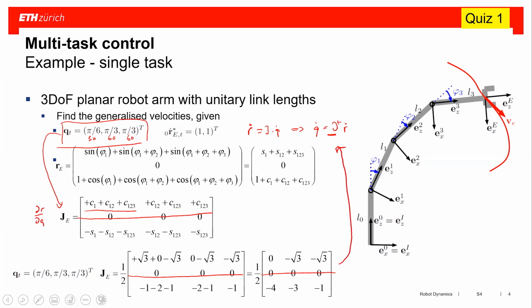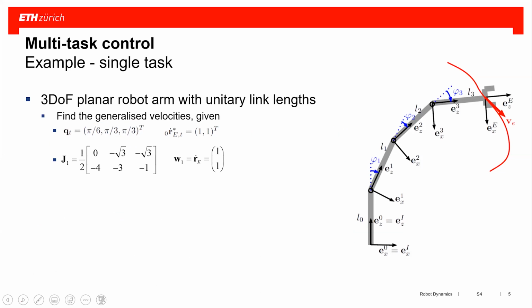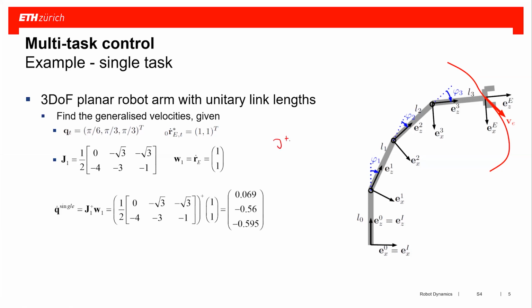All right, now we have the Jacobian, and all we need to do is take this and evaluate this formula up there. So we have to take the pseudo inversion of that. This is straightforward. So the pseudo inversion J plus is equal to J transposed times (J J transposed) to the power of -1. So what we're doing here is creating, with this J transposed, a square matrix which is invertible. Then you invert it, then you do a Jacobian transpose pre-multiplication.